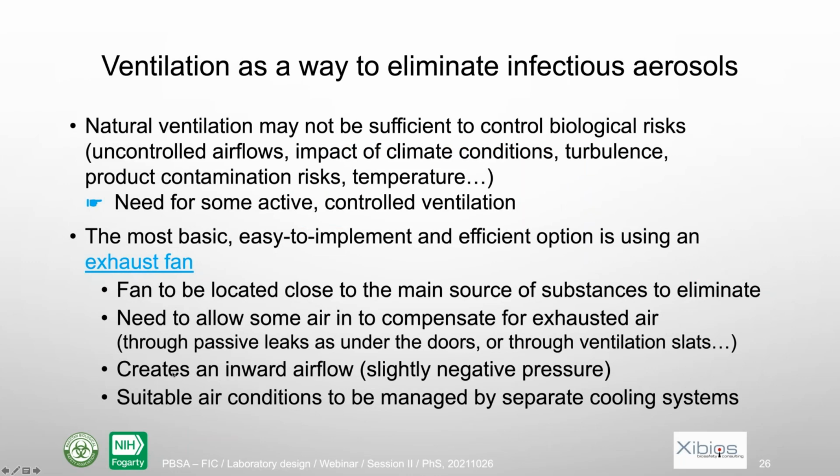If you put in an exhaust fan, you create an inward airflow, which gives a slightly negative pressure, which is generally a good measure, especially if there is some kind of spill and so on. You will not spread it immediately to the outside. But still, if you use an exhaust fan, you might still need a separate cooling system in order to ensure the right temperature in the lab.